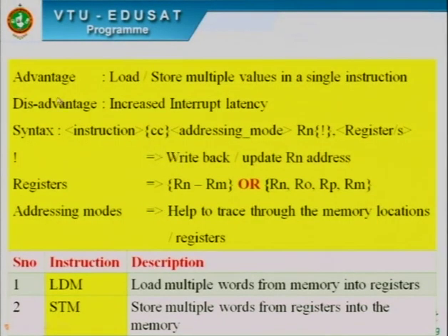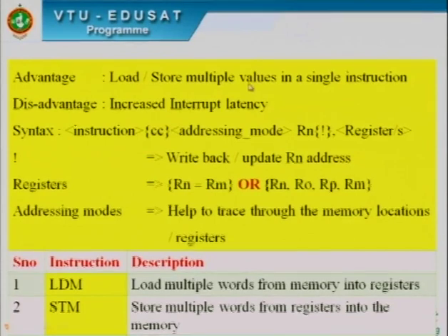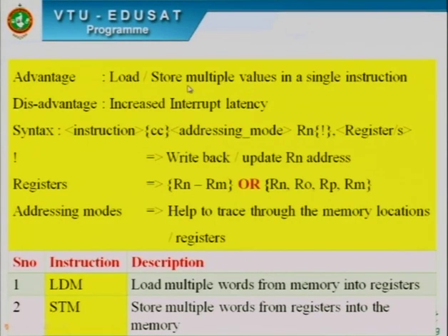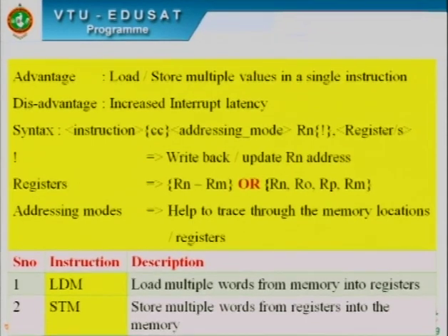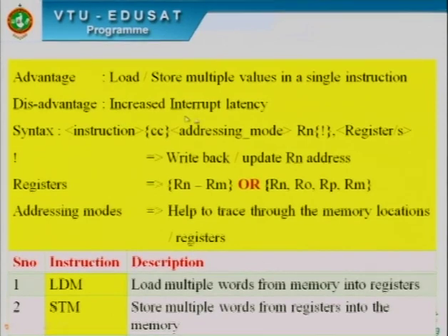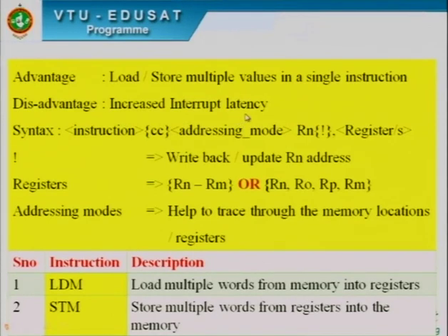Let's start with this. The advantage of this instruction is we can load or store multiple values in a single instruction. But there is one disadvantage with this instruction. The disadvantage is that it increases the interrupt latency. Latency is the time duration between the occurrence of the interrupt and the beginning of the ISR, interrupt service routine, execution.